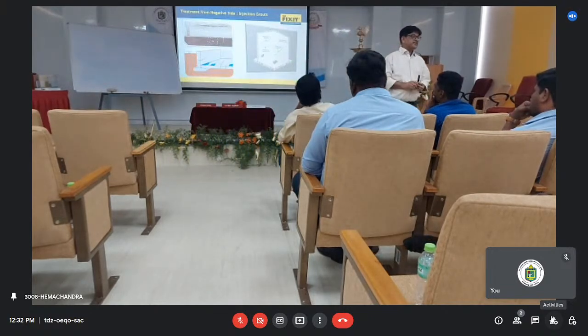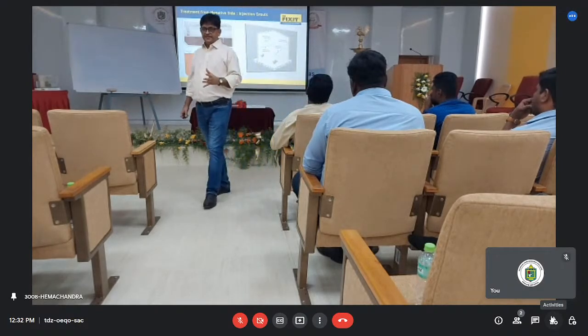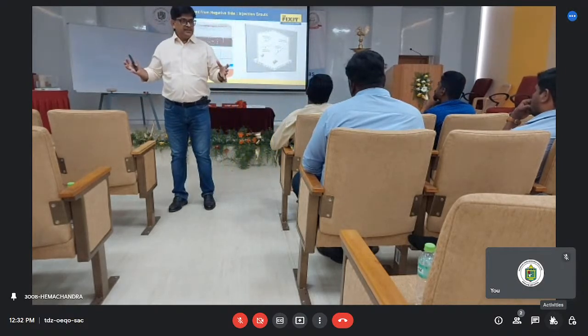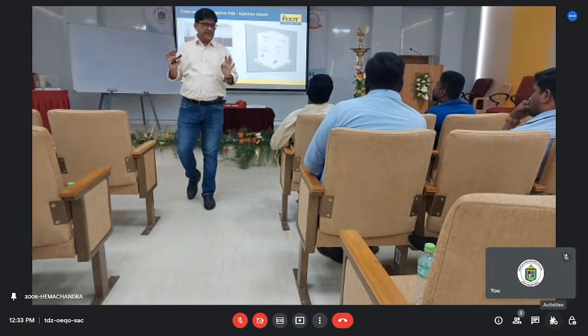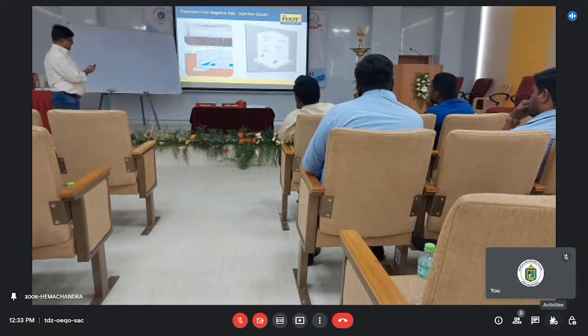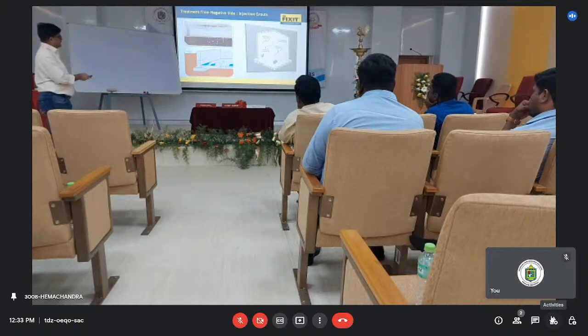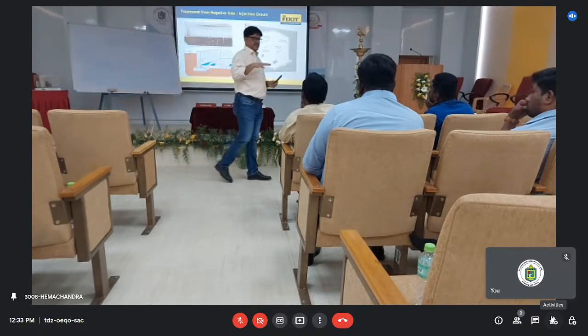These are all positive side. Negative side protection has to be integral. We have to build it up. Once it is done integrally, then we can do something on the negative part, and we can do an internal treatment. Okay. So when these kinds of issues are there in the basement, plus there can be cracks on the surface, construction joints here, cracks here, all that. The process normally to be followed is injection grouting.